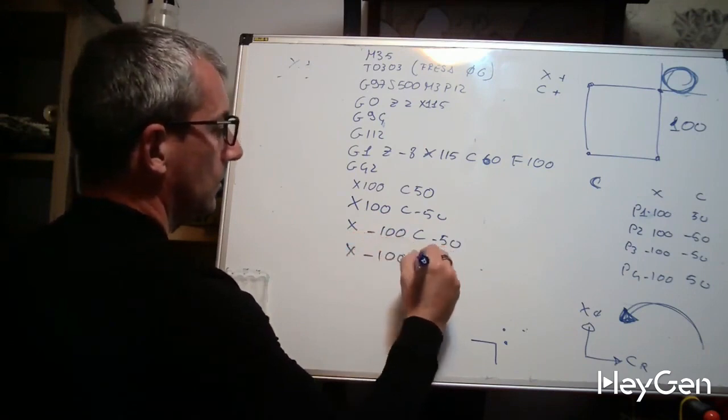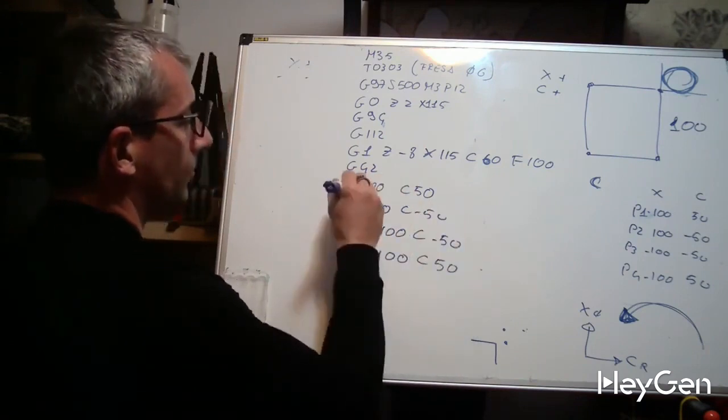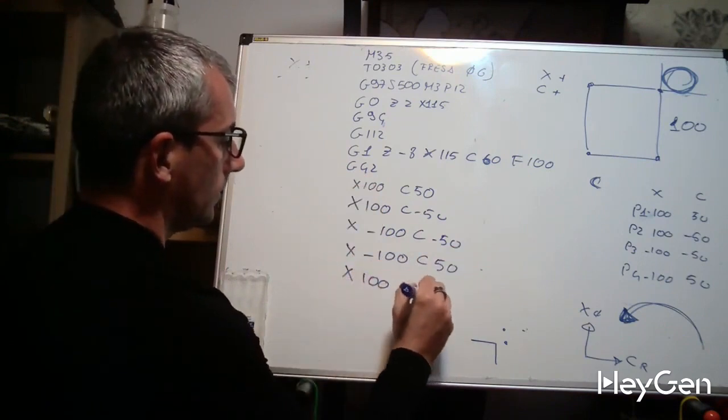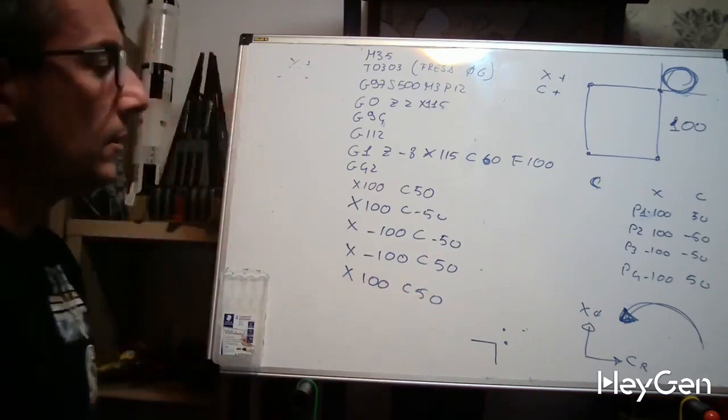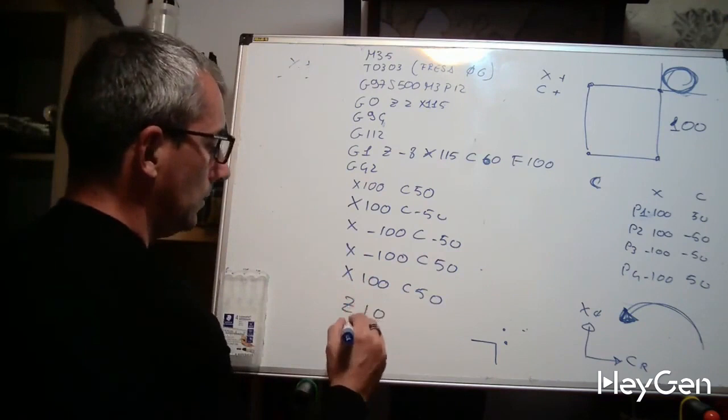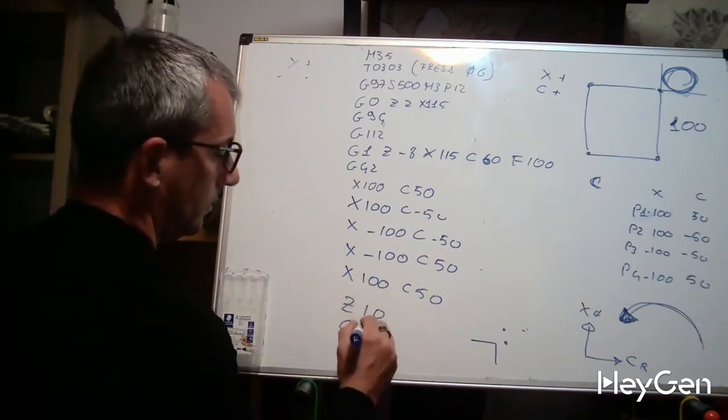Stop spindle. As we made a square, we can make a hexagon, a triangle, or add a radius R10, R10 to round 2 edges, 3 edges, 4 edges as needed. If we need to round the 4th edge, return over one side or it won't round the 4th edge.